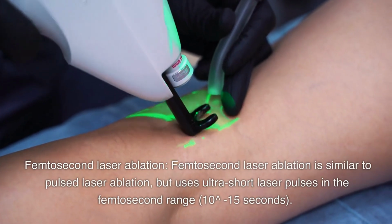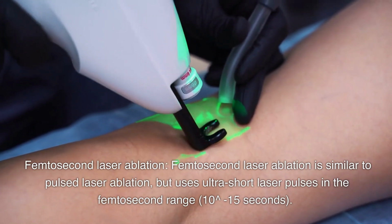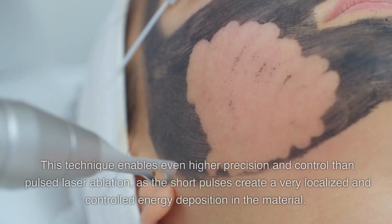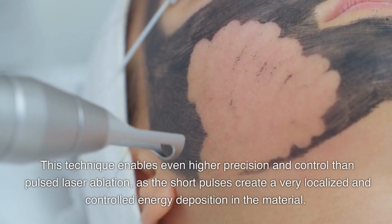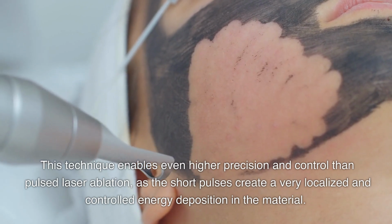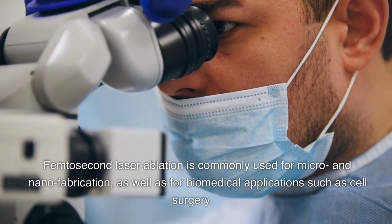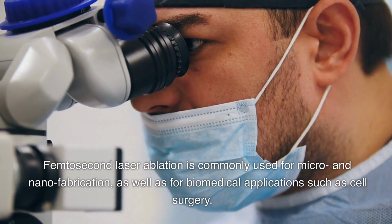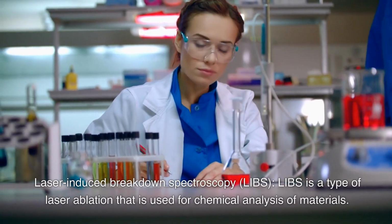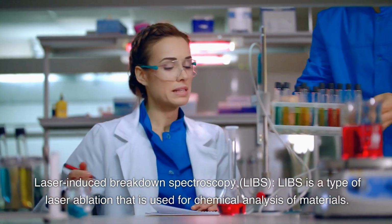Femtosecond laser ablation. Femtosecond laser ablation is similar to pulsed laser ablation, but uses ultra-short laser pulses in the femtosecond range, 10^-15 seconds. This technique enables even higher precision and control than pulsed laser ablation, as the short pulses create a very localized and controlled energy deposition in the material. Femtosecond laser ablation is commonly used for micro and nano fabrication, as well as for biomedical applications such as cell surgery. Laser-induced breakdown spectroscopy, LIBS, is a type of laser ablation that is used for chemical analysis of materials.